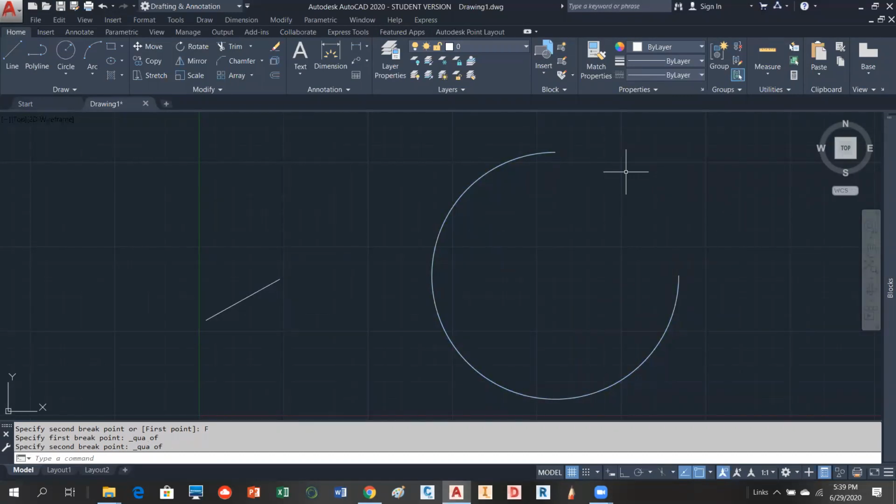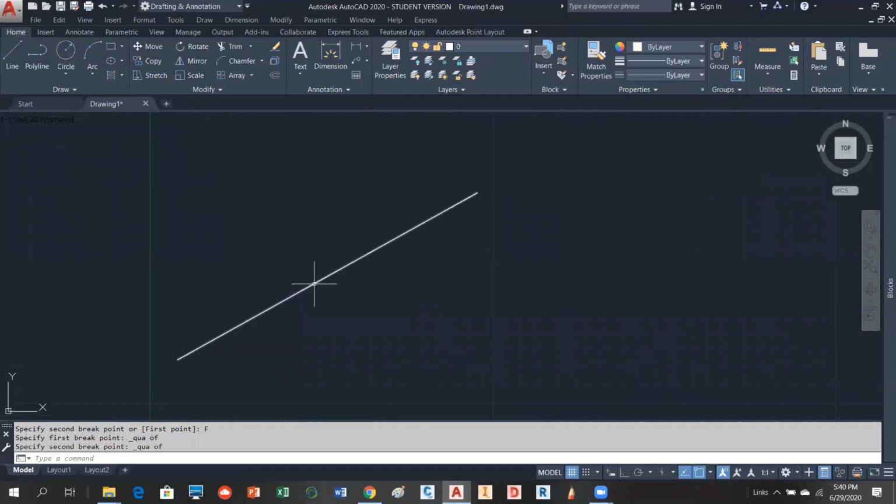Now, here is absolutely one of the coolest things you can do with break, and there is no other way to do this in AutoCAD. And that is to break an object such as this line at a point such that the two objects that result from the break are going to be touching each other endpoint to endpoint, okay? So again, when you break it, you're not removing a little tiny piece between, okay? So they are going to actually be physically touching endpoint to endpoint, okay?